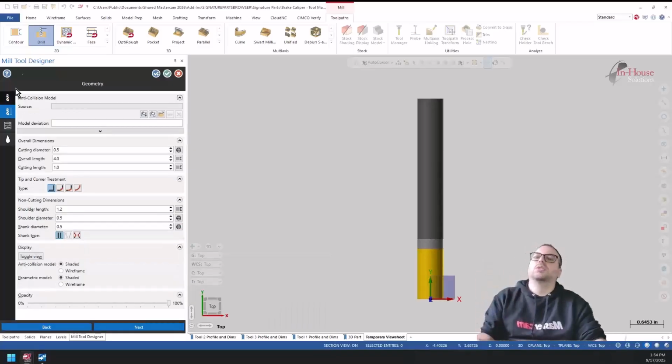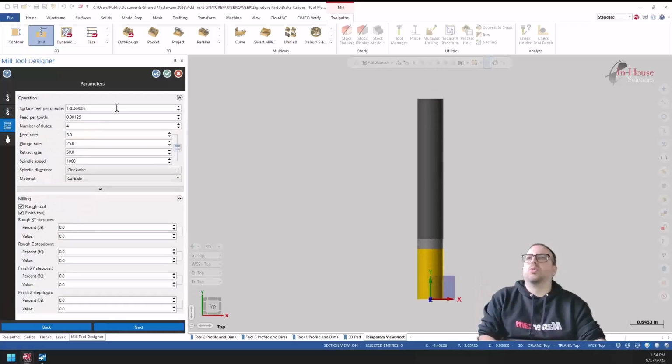And then if you go into the next tab, you have again the same options. The wording might be a bit different, but mostly it's the same stuff, where you can set your flute length, your shoulder length, and all that stuff. And after that you have your parameters for feed rate, plunge speed. One little thing that's also new, for the step over, it's now not automatically a percentage. It could be a percentage, but you could also set a value, which sometimes was a bit tricky to get down to a specific percentage.